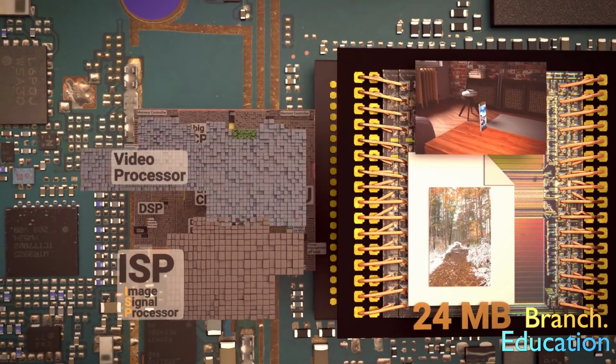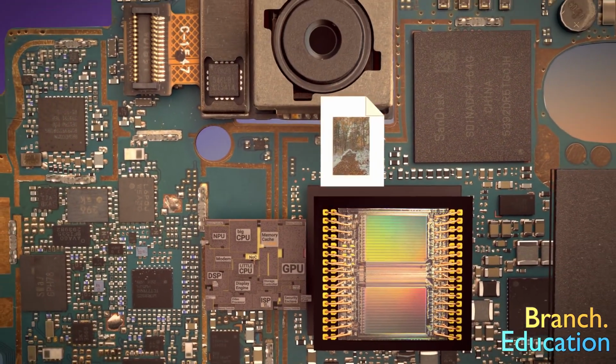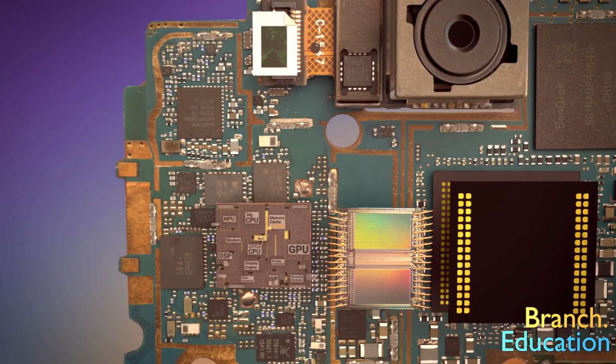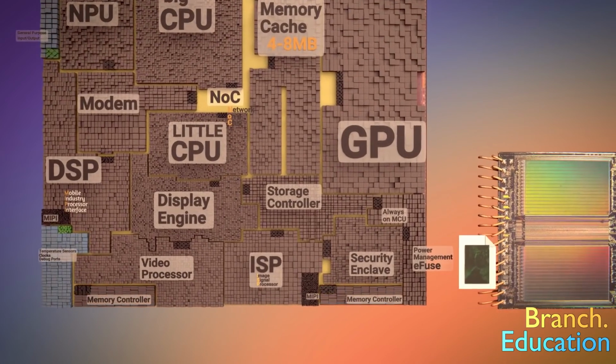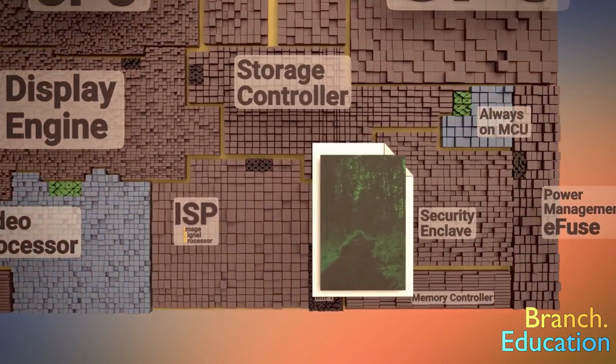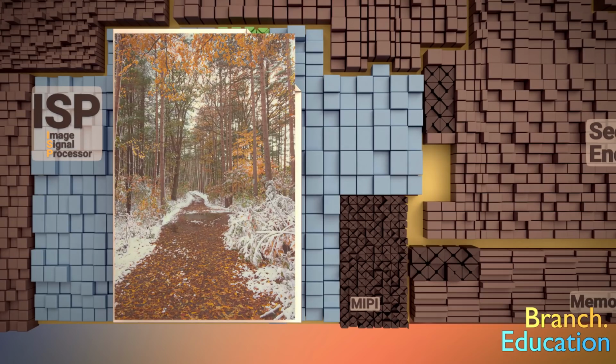Okay, let's get back to the raw image data of the picture that was taken by the camera and then sent to the MIPI, routed through the SoC, and stored in the DRAM. The next step is for the image signal processor, or ISP, on the SoC to read the raw uncompressed image data and perform a number of image processing steps.